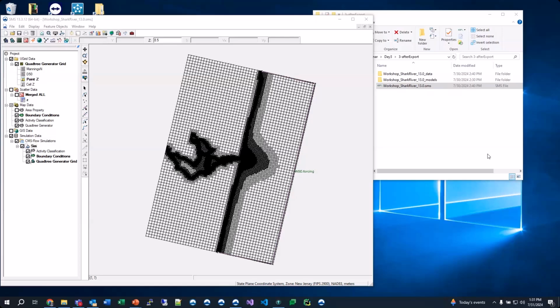So I think there is something done actually changing the way the sediment is moved in different ways with those first two factors. And then, as you said, that morphology acceleration factor is just a multiplier. It takes whatever was moved and increases or decreases it by that amount. I think that's how it is done. Like I said, we have somebody really looking into that morphology acceleration factor this fall, and hopefully by the spring we'll have a much better understanding of exactly how it's implemented and when the better times are to use it.